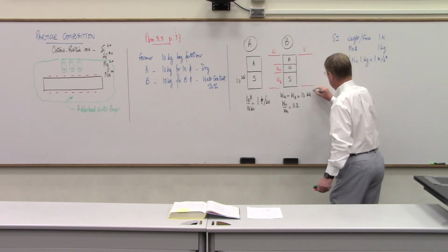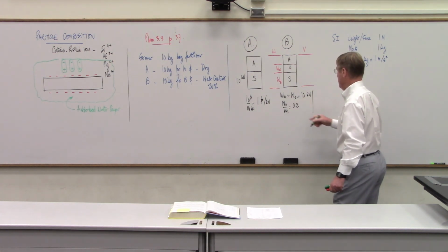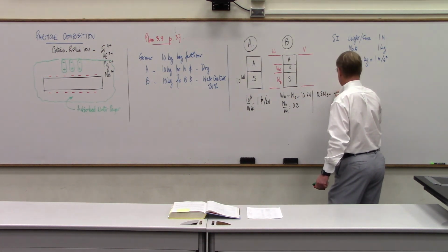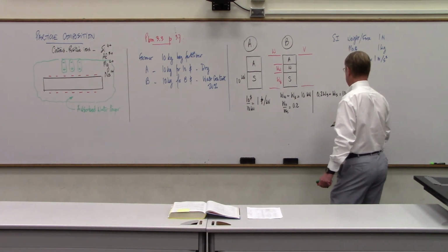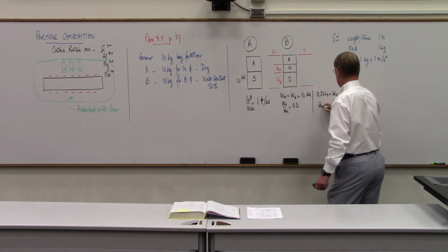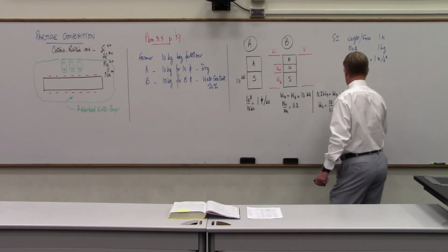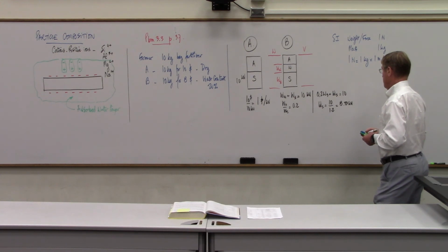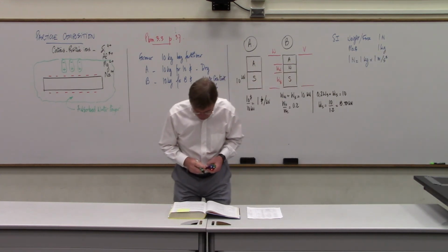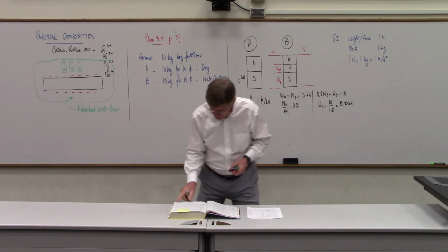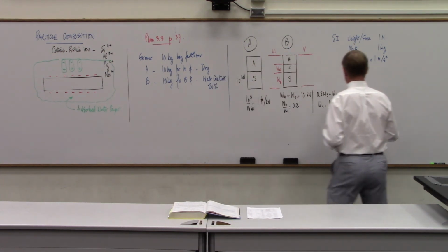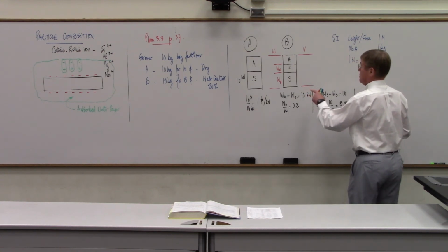So then if I take those two things, I can go back to this equation and do weight of water equals 0.2 weight of solids. So I've got 0.2 weight of solids plus weight of solids equals 10, or that's 1.2 weight of solids equals 10. Weight of solids equals 10 divided by 1.2, which is 8.33, I believe, kilonewton. Let me double check, I think that's right. This page, 8.33, yeah.